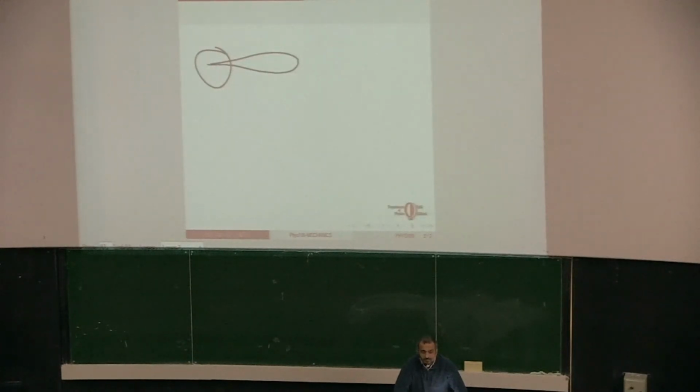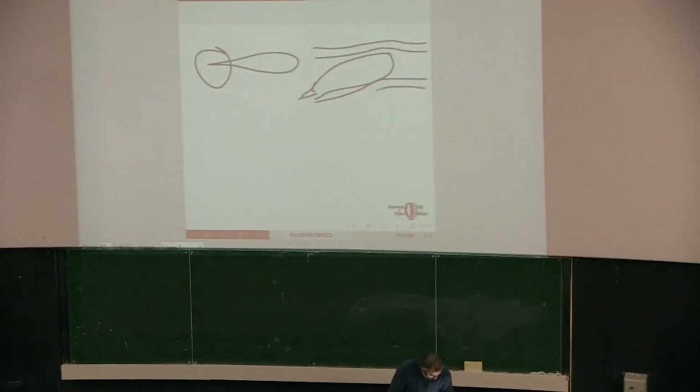Now you can say it's increasing the velocity by squeezing it in the top part of the wing. In this shape, this is quite symmetrical, so the velocity and the pressure in the upside and the downside will be equal. But when it goes in this sense, we had seen that the lines are being squeezed at the top than on the bottom. On the bottom, the lines are more or less homogeneous. The lines are squeezed. So here, they are moving faster.